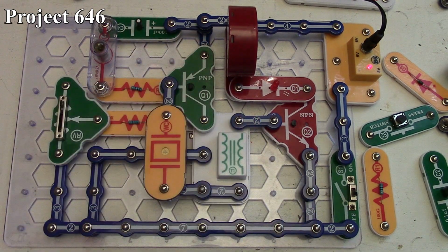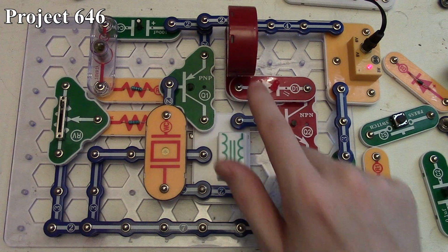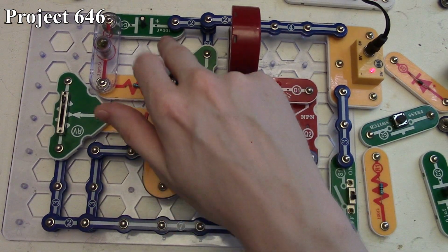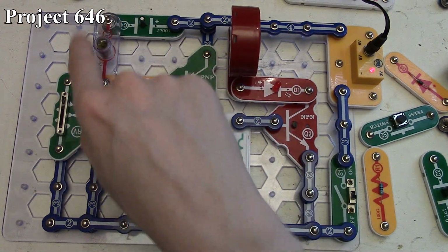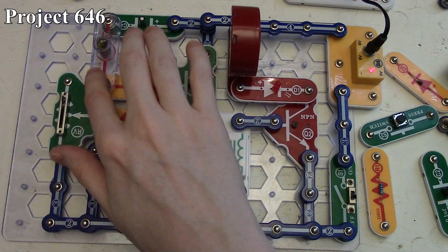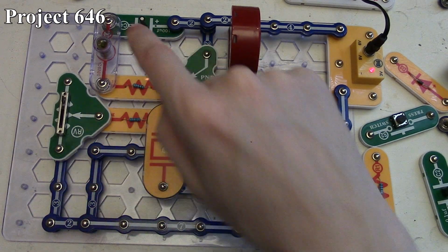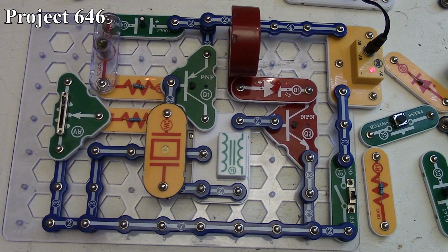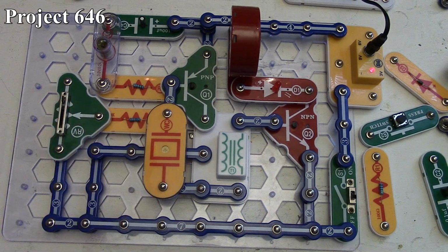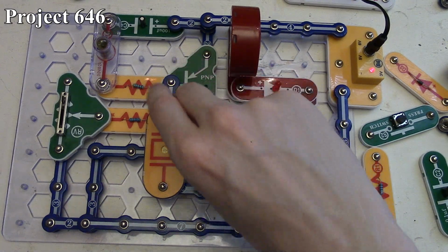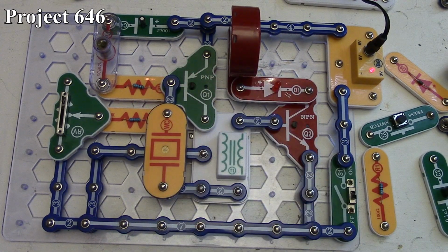And on the other side, we have the actual oscillator circuit that we're going to be hearing and seeing. So we have our 100 microfarad capacitor being fed, and then it runs through our 2.5, 3-volt lamp here, pretty much acting as a snap. And then it goes through one of our resistors into the base of our PNP transistor, which then turns the PNP transistor on and off. We have our variable resistor, again controlling resistance to another resistor that is across our whistle chip and also the base of the PNP transistor here. And then these ground connections are all going into our transformer.